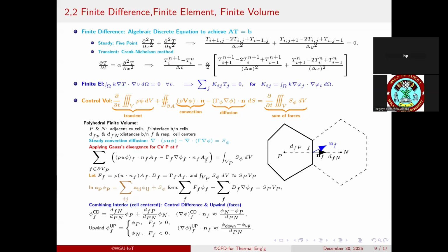In contrast, first order upwind accuracy checks the maximum of the flux, the upstream fluxes from either side of the face based on the upstream cell flow value, depending on flow direction.